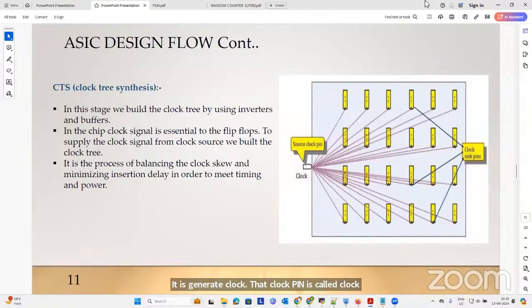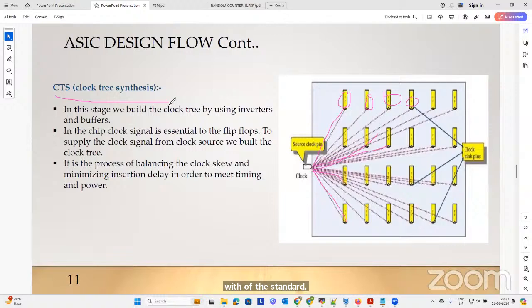And all these yellow colored ones are standard cells which are placed in the core area. Routing the nets to each and every clock pin of the standard cells is called clock tree synthesis. There are different types of clock tree algorithms, and the most used one is the balanced clock tree.